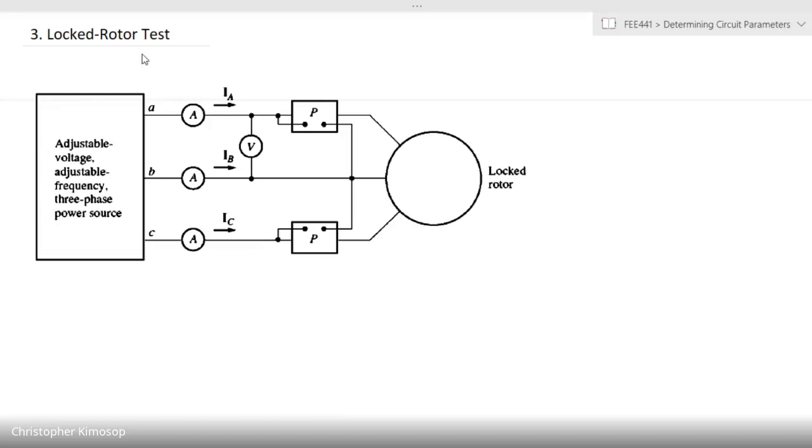In the no load test, we were allowing the motor to run freely without any load being applied to it. When you look at the locked rotor, the opposite happens. We apply a brake such that you are powering the motor, but the shaft is not free to rotate. You have locked the rotor. So what happens in this case? You are supplying power, but the power has nowhere to go. And what would be the impact of that? Let's look at the impact of that.